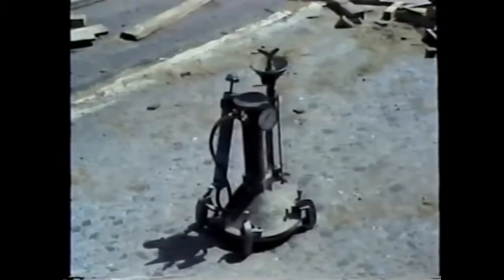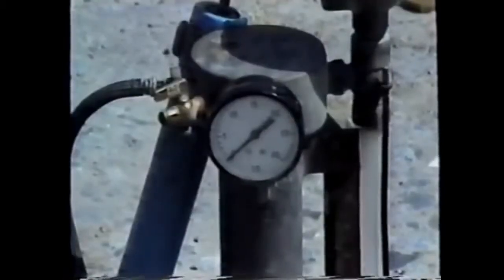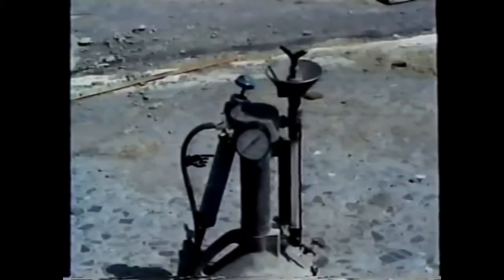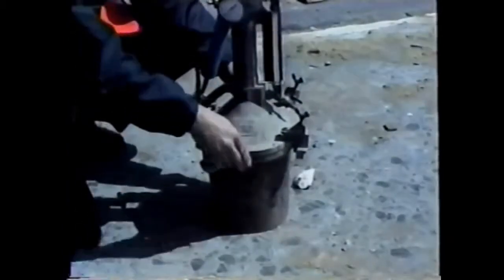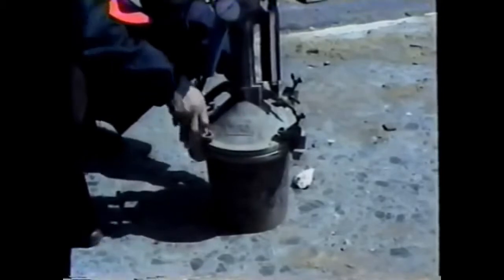The meter consists of a measuring bowl having a capacity of at least 2/10 cubic foot and a cover assembly that includes a standpipe, a pressure gauge, and an air pump. The cover assembly also contains a number of valves and petcocks. The bowl and cover must clamp together to form a pressure-tight seal.